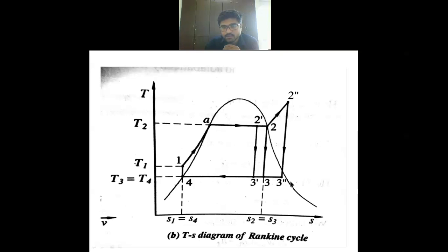Suppose this sg at condenser pressure was 8, and what answer did we get for s3? It was around 6. So basically it is less than this sg. That's why we can apply the formula that we have used in this example.